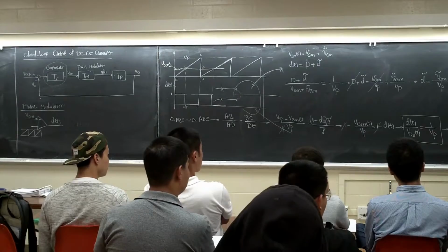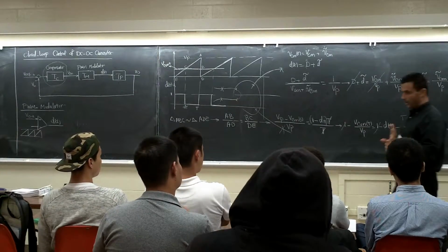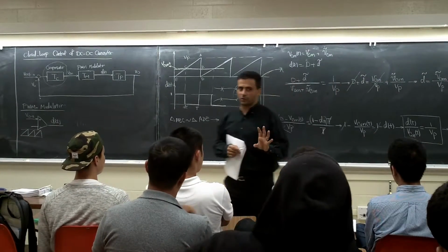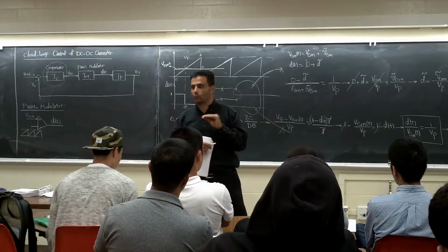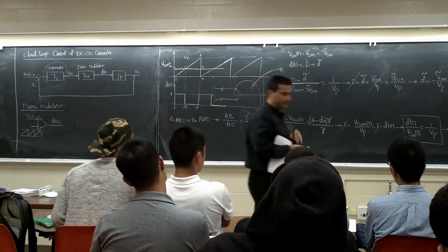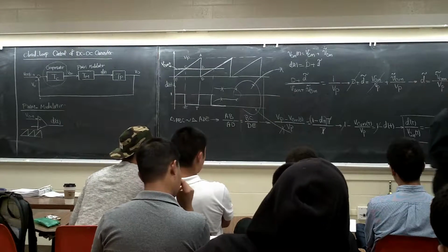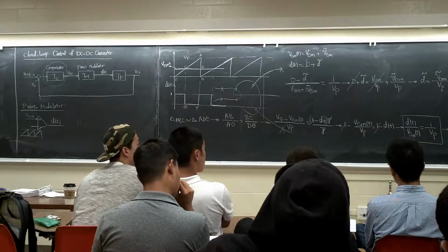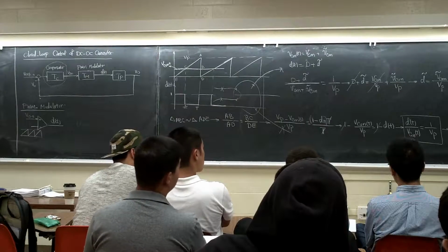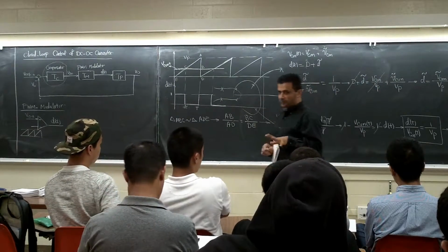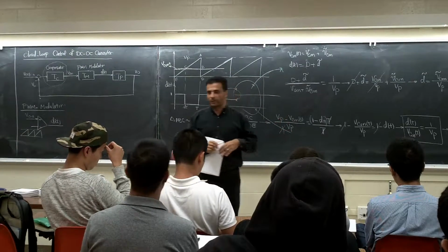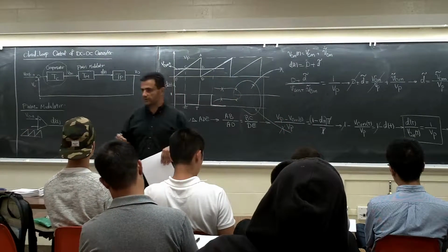To have a good system, stability-wise, we want a phase margin of 45 to 60 degrees, something like that. You learn this as a rule, 45 to 60 degrees. But you can go read the control books, and all of them mention something with a 45. The higher the phase margin, the better, but it's very difficult to get more than 60 degrees. The parameters are going to get unrealistic. But 40 to 60 is a good number.